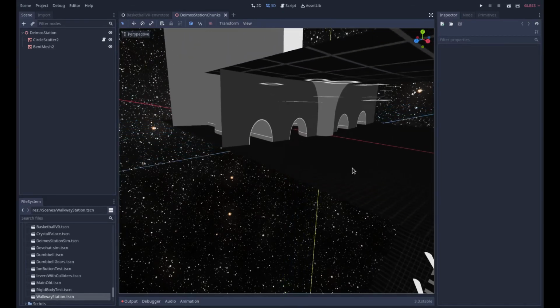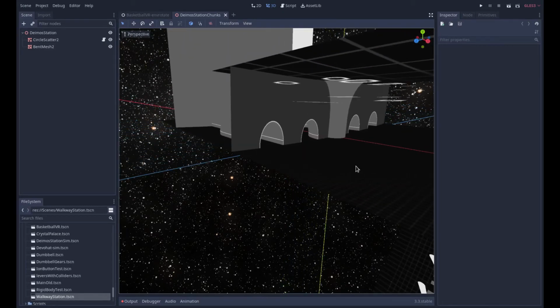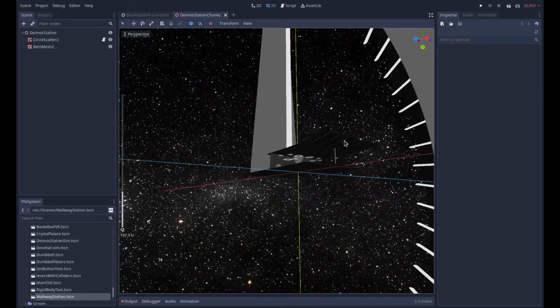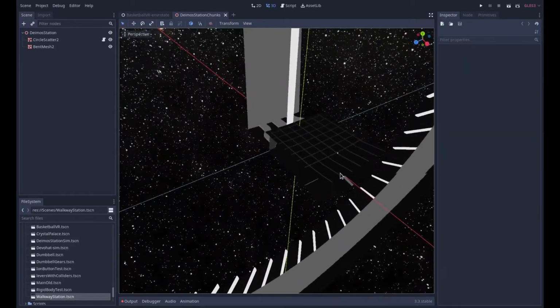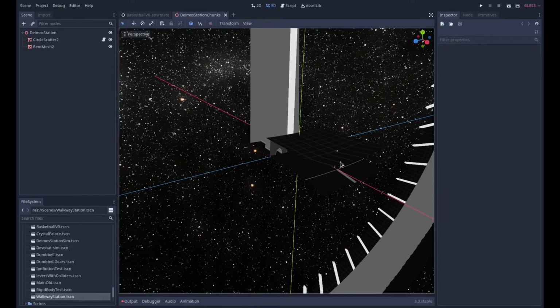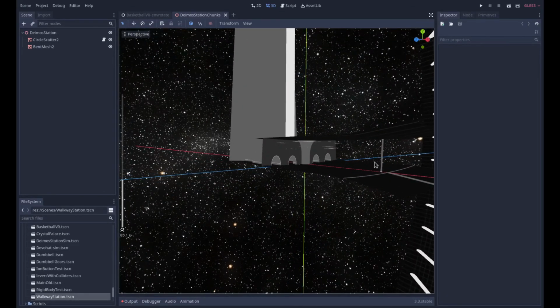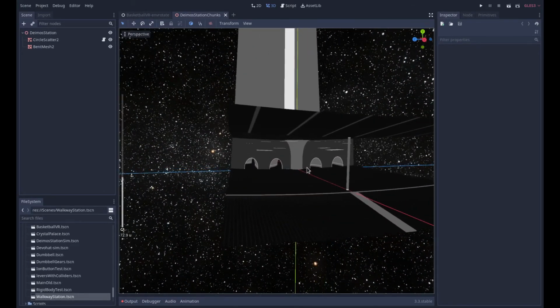So when you have such a wide clipping range, what happens is that when you try to render things that are super far away, two planes that are close to each other, let's say you have one thing that's on top, you end up having kind of a fight. The rendering fights between whether it's supposed to render one or the other because the resolution's not big enough to keep track at such a distance what's on top of what.